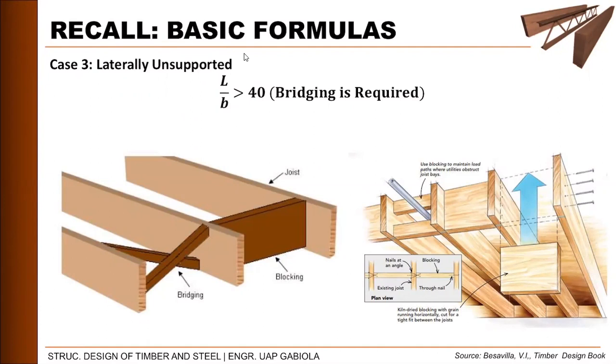Okay, so our length will be reduced in half. So you can put your bridging at the center or at third points, at fourth points.